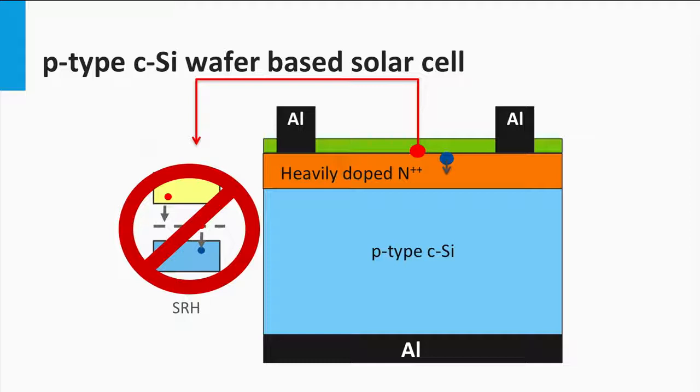Increasing doping levels decreases the diffusion length of the minority holes in the emitter layer. Here you see an example in which the diffusion length has become so small that the minority charge carriers are unable to reach the p-n junction. Therefore, too high doping levels or too thick emitter layers would result in a poor blue response, or in other words, low EQE values in the blue part of the solar spectrum. Such a layer could be referred to as a dead layer, as the light-excited minority charge carriers cannot be collected.